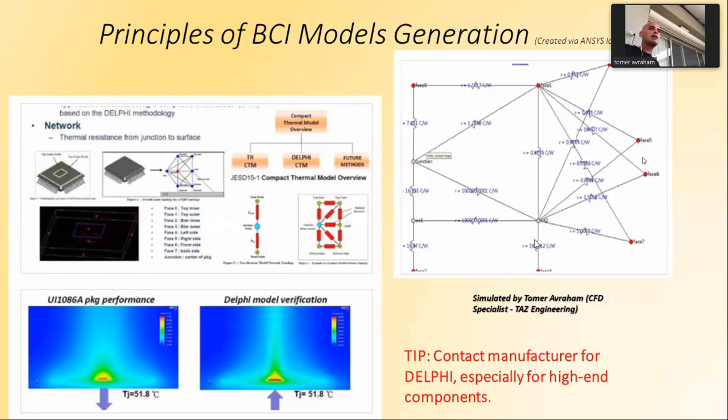Okay, you ask, I have the Stratix 5, and I want a Delphi model for iSpec or for FloTHERM, and they would supply you with the model. I mean, all the time. They can give you these numbers, the theta JC and theta JB, but they will supply you with a Delphi model. Then you could get very accurate results, almost as if you use the detailed model.